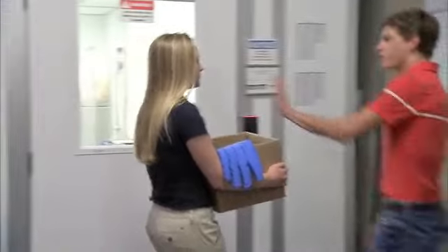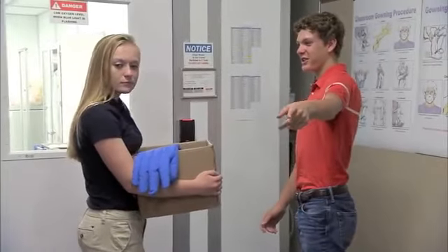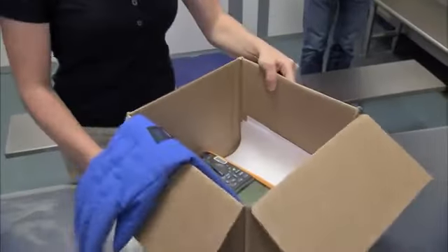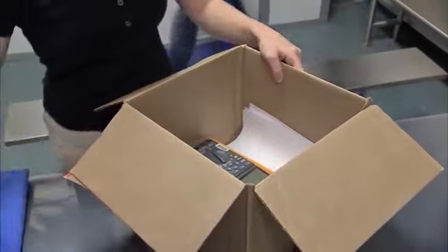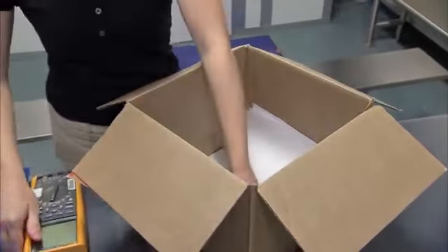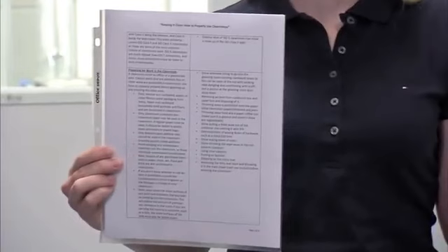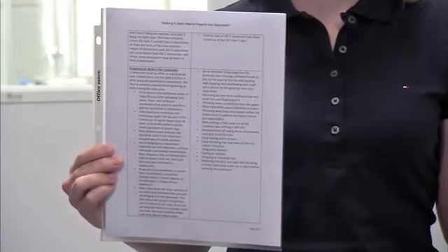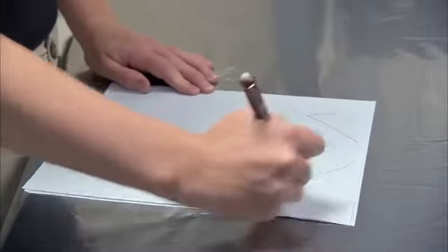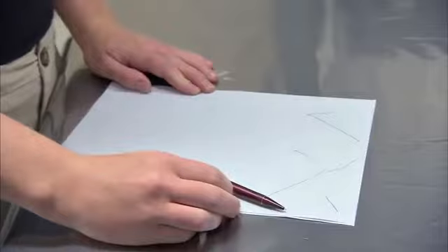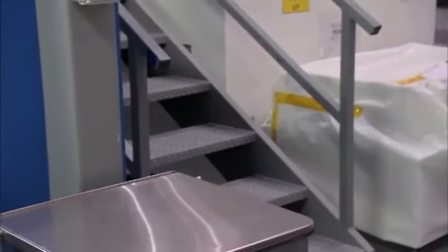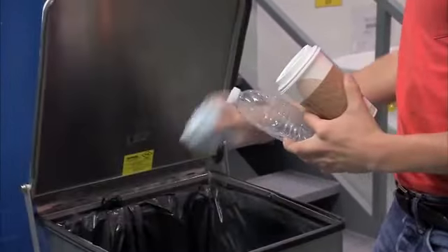First, remove any cardboard, paper, or other fibrous outer packaging from items. Paper and cardboard excessively shed particles, and fibers are prohibited in clean rooms. Only cleanroom notebooks and cleanroom paper may be used in the clean room. If regular paper must be used, it should be sealed in plastic sheet protectors or plastic bags. Only ballpoint pens without caps should be used in the clean room. Graphite pencils create particles.